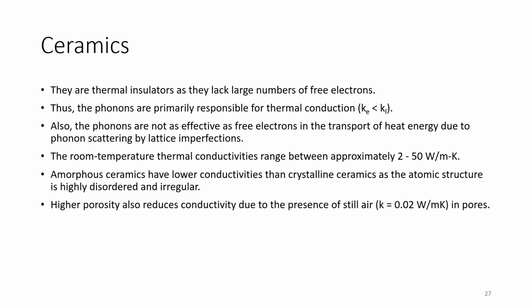Next we have ceramics. These are thermal insulators as they lack a large number of free electrons. Thus the phonons are primarily responsible for thermal conduction, so Ke is lesser than Kl in this case. Also, the phonons are not as effective as free electrons in the transport of heat energy due to phonon scattering by lattice imperfections. The room temperature thermal conductivities range between approximately 2 to 50 watts per meter Kelvin.